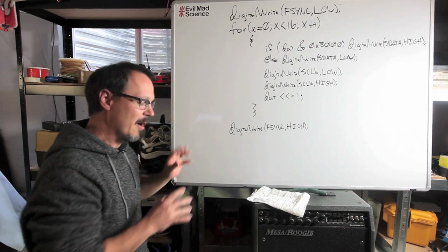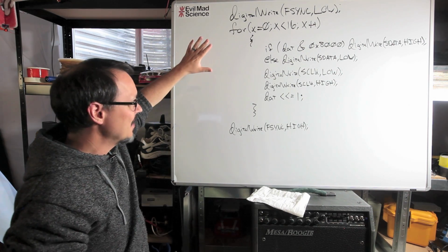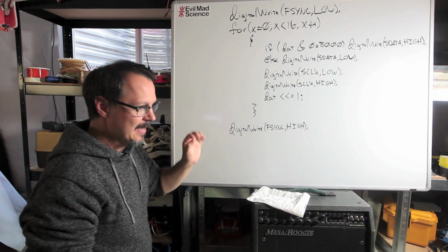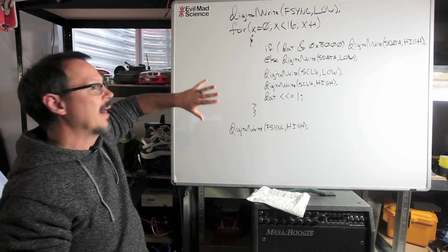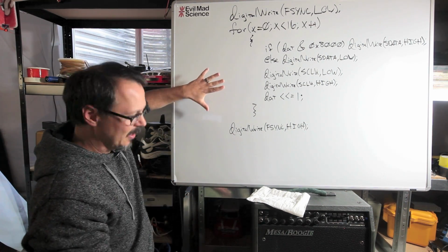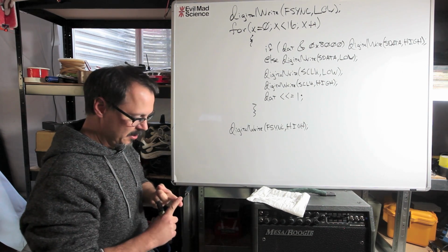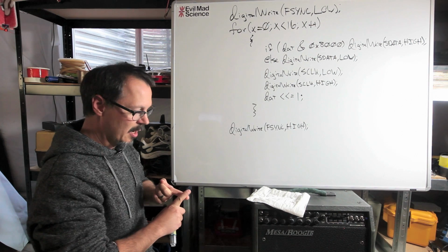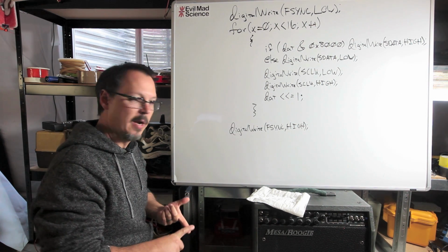So this is the pertinent code for talking to the AD9837. This is an example of a single 16-bit data transfer to that part. This is the bitbang. I did not use the Arduino SPI library. To bitbang like this, you have to go back to the timing diagram I showed you before. Two things to note. Number one, the clock frequency on the Arduino Pro Mini is 16 megahertz.